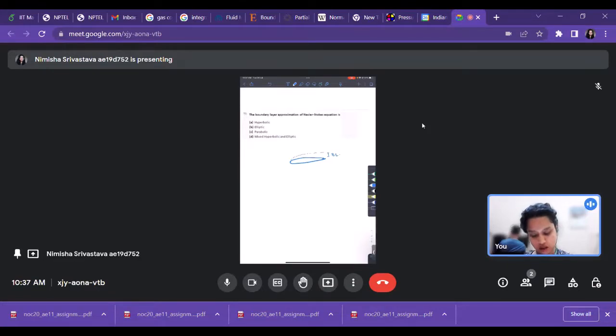So basically, what this boundary layer is, is an area of very high gradients. You know that at the wall we need the no slip condition to be active for velocities u, v, and w, and so that's a very drastic change from the free stream velocity, because in the free stream, that is outside of this boundary layer, the velocity is going to be of the order of u infinity, which is going to be high. So going from u infinity directly to zero is a big jump. This area of high gradients is known as the boundary layer.